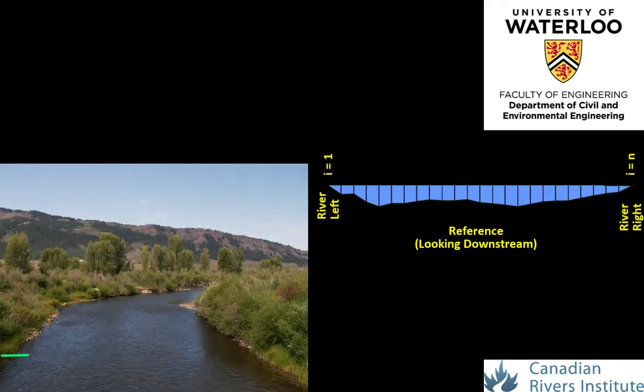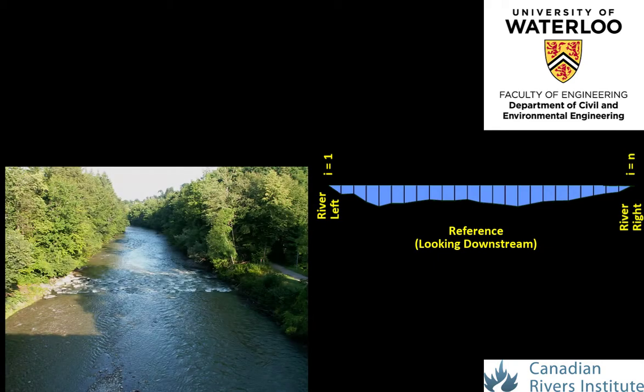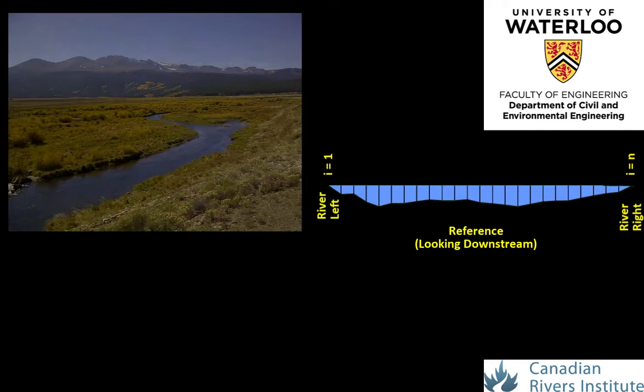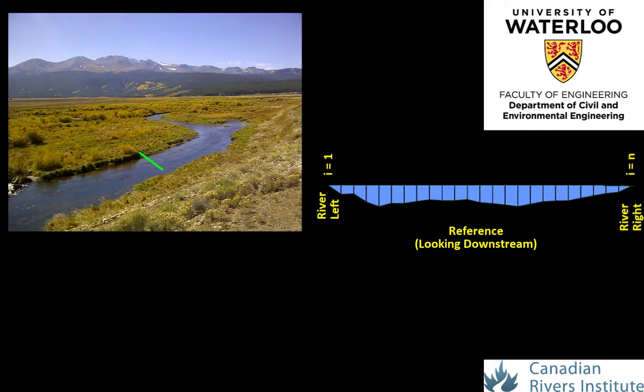The cross-section location should be away from obstructions such as beaver dams, debris jams, or boulder clusters, and conform as best as possible to the natural cross-sectional shape of the channel, both upstream and downstream. Avoid highly turbulent regions to reduce the potential of velocity bursts during the velocity measurements. Measurements should be taken in relatively straight sections of the channel, typically between bends such as on riffles or runs, where more parallel flow line assumptions and hydrostatic conditions of the water surface can be more readily made.